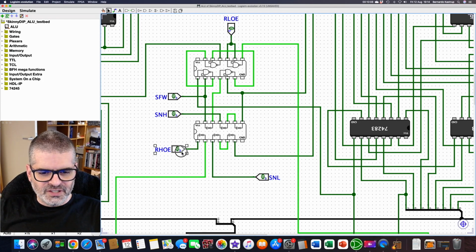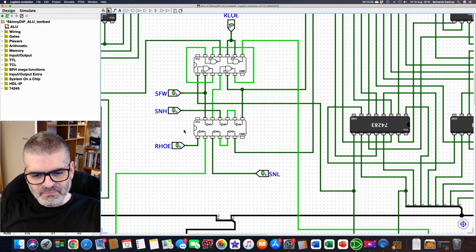But this signal needs to be inverted, and this signal here needs one inverted version, this one here. It needs an inverted version. And since this NAND gate is already taken, I needed to invert it somewhere else. So I needed an inverter. So why would I choose a 7404 if I can choose an identical 7414, which does have the Schmitt triggers? So that's what I did.